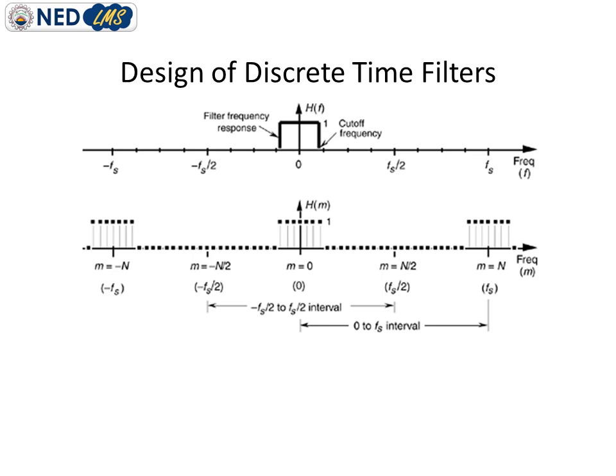For this, we can just take the DFT or FFT of this frequency response to get the time domain impulse response. As we already studied in the previous lecture, the time domain impulse response is related to the frequency domain frequency response, as both of these are transform pairs.